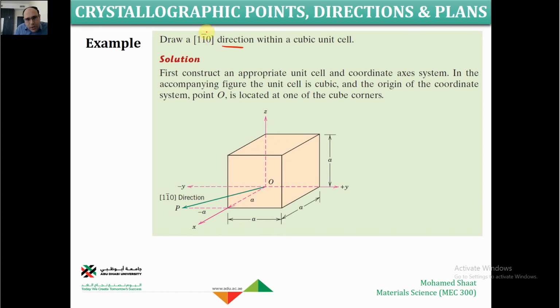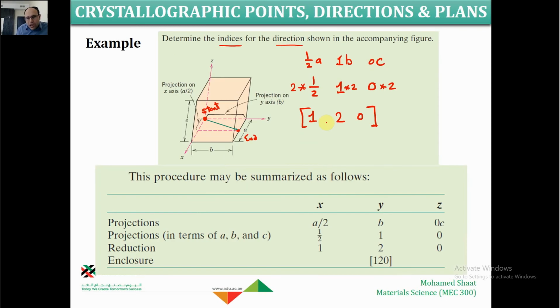So I have to think about this crystallographic direction. We do have something new here, which is this bar on top of this index. This bar indicates that this index is -1. So for example, I can write this one as 1, -1, 0. You got my point? But in terms of the representation of the crystallographic direction, this is not preferred, because I could deal with this like a dash, not a negative. And as I mentioned, we basically don't add spaces here.